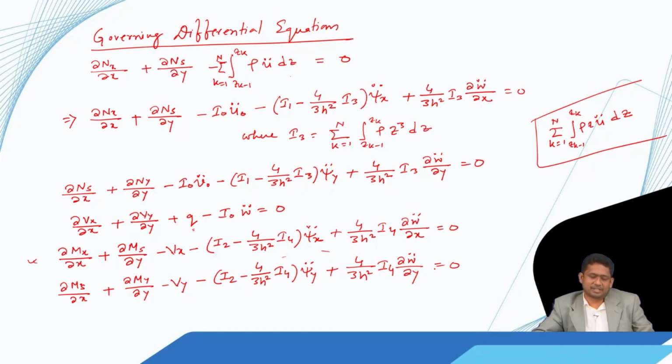So, for that, instead of writing this differential equation, we write the corresponding energy or virtual work equation and then put our assumptions there, and then we say that the coefficient of each of the variation terms is 0, and by setting them to 0 we get a set of algebraic equations for the static problem, or an eigenvalue problem for buckling or the free vibration problems, and then by solving those we can get our desired quantities.